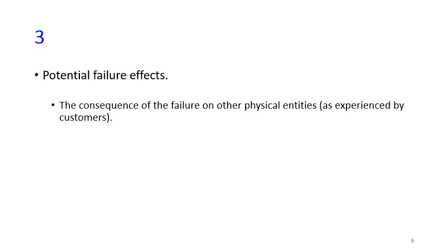Continuing from the second column, where the design team has already identified the potential failure modes, in the third column the design team should think about what the effects of each failure mode are. So if this fails, what are the effects? And those effects are written in column 3.